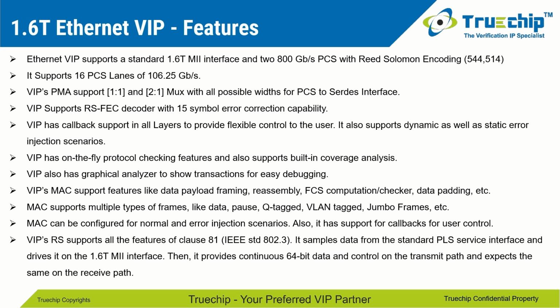VIP's MAC supports features like data payload framing, reassembly, FCS calculation, and data padding. MAC supports multiple types of frames like data, pause, queue tagged, VLAN tagged, jumbo frames, etc. And also, the MAC can be configured both for normal and error injection scenarios. It also has callbacks for complete user control.